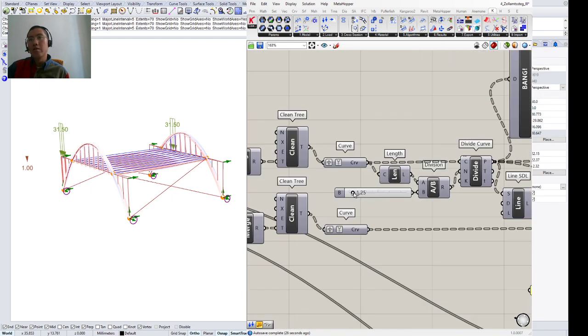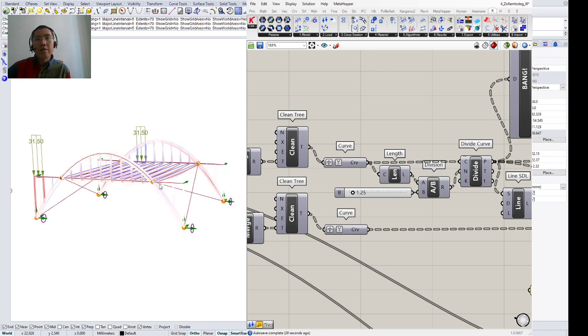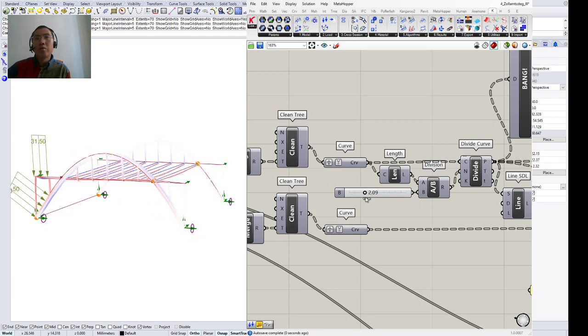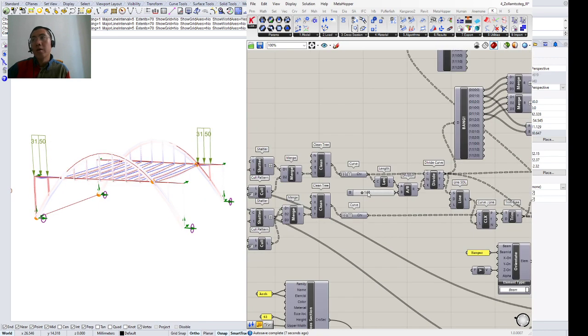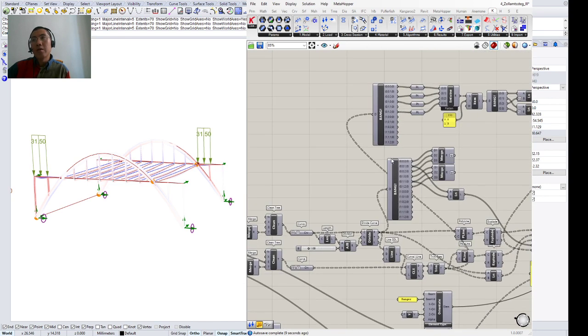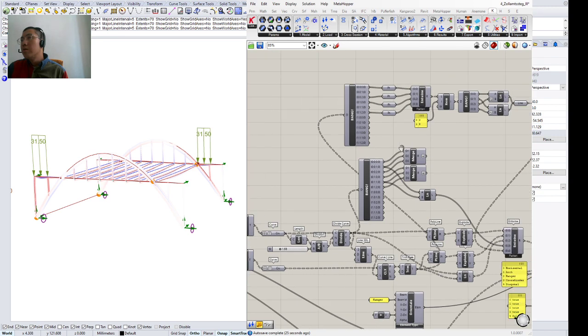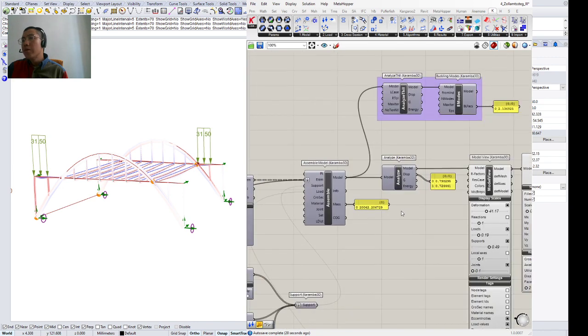And we can also change the division between each of the hangers, for example, which might also have an effect on the diagonal members, as you see, because of the way that the script is set up. Some of the elements are manually inputted, which are these diagonal elements there. So basically with this example, we have built up this whole bridge.